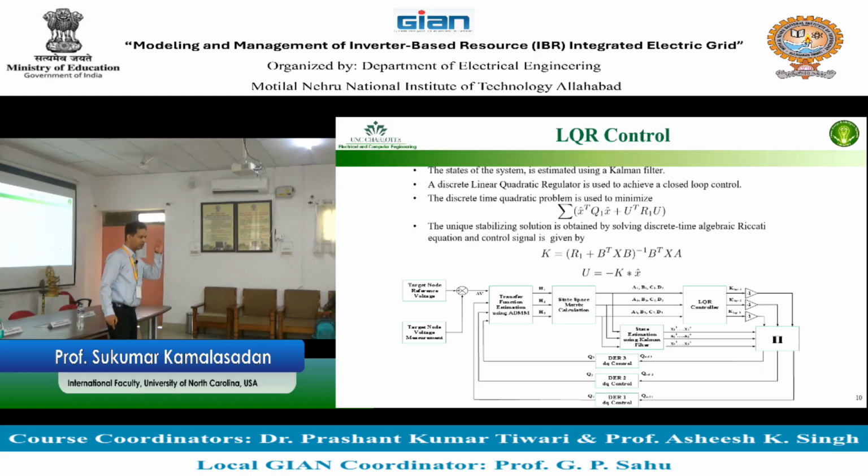That node voltage can be constant or changing with respect to time. We are talking about changing with respect to time for one node. We can also call this a profile. So you have a target node and a measured node at that position, and then you take this delta V and give that to a control architecture. The output of the control architecture is a reference set point, or Q, going to the inverter.